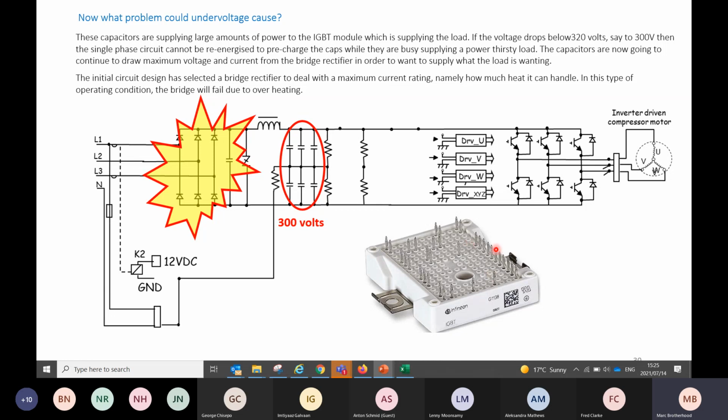Not because of over voltage, not because of a gecko running over a board, purely because either an impedance is incorrect. This line might be measuring 1 ohm instead of 0.1 ohm, or at lunchtime, too many people are plugging in single phase. Your whole inverter board is going to blow because the voltage has dropped too much, because this load is very thirsty and it wants constant power.